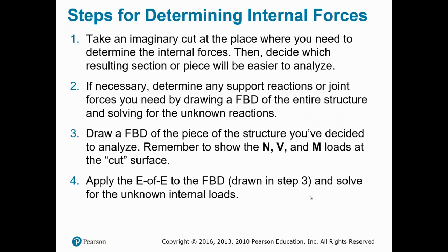Steps to determine the internal forces. Step 1: we take the imaginary cut at the place that you're interested in, and then decide which resulting piece will be analyzed, whichever side will be easier. We're going to use that side to do our analysis. Step 2: we determine the support reaction forces for the entire structure. Pin support, roller support, whatever is going on, we figure out the support reactions for any unknowns for the entire structure.